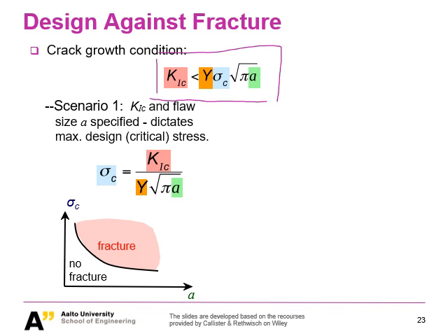And then you could say, if we want to design against fracture, we basically need to have a little bit smaller critical stress, right? And that is finally correlated to, let's say, your loading. Yeah. So this is typical for your loading design. Don't go over to the fracture limit, but always stay with the no fracture part.